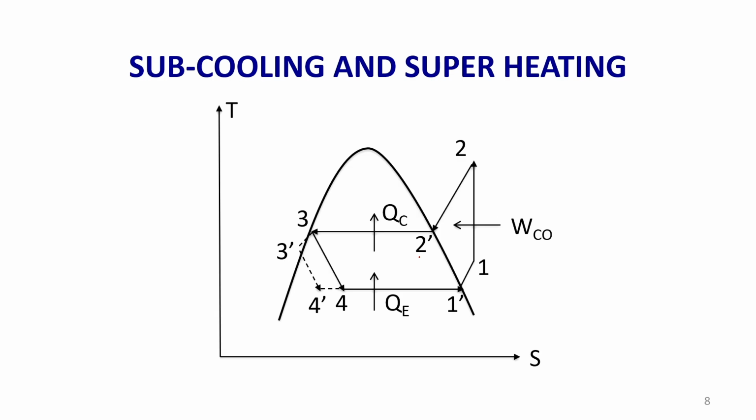We will see the same base problem which I have solved in the previous lecture. I will be adding some more data like a degree of subcool or a degree of superheat, whatever it is, and we will see how the COP varies. Subcooling and superheating.